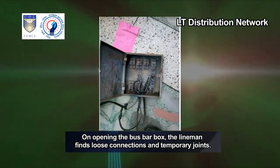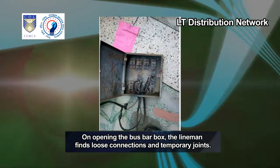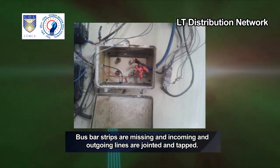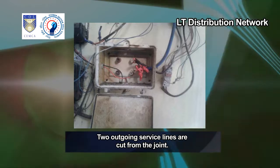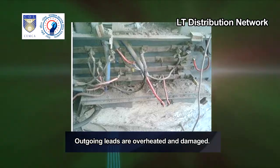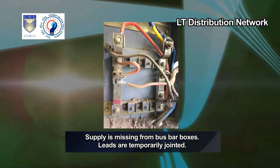On opening the bus bar box, the lineman finds loose connections and temporary joints. Bus bar strips are missing and incoming and outgoing lines are jointed and tapped. 2 outgoing service lines are cut from the joint. Outgoing leads are overheated and damaged. Supply is missing from bus bar boxes.